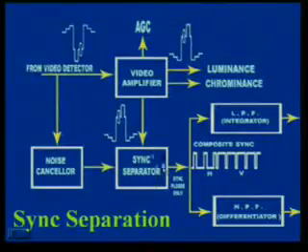The sync separator gets the information from the video amplifier as well as the inverted pulses from the noise canceller, because if you invert these two pulses, they will cancel each other.